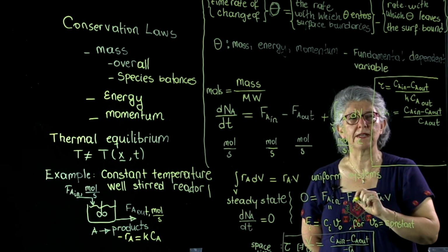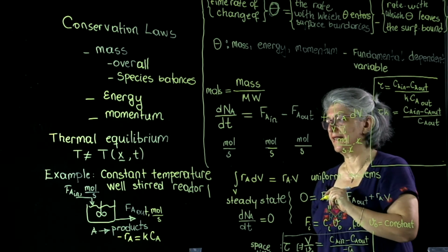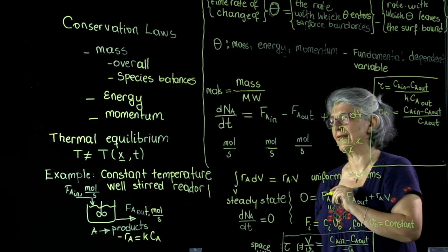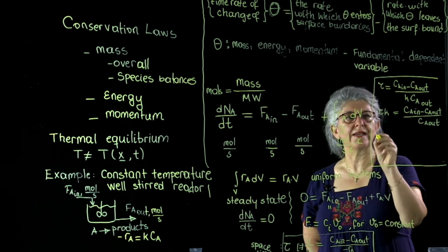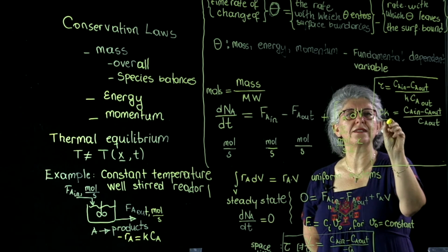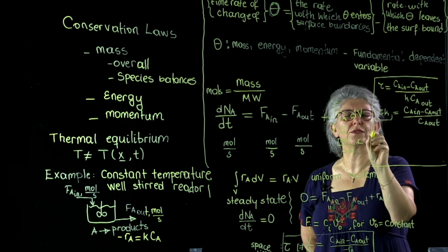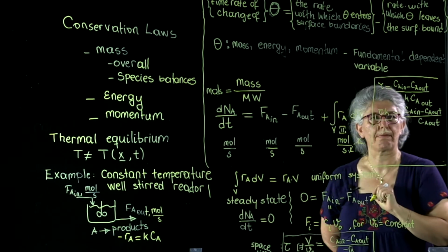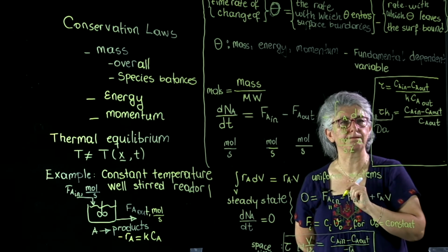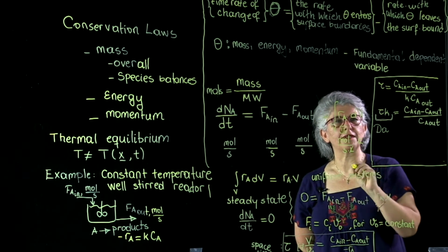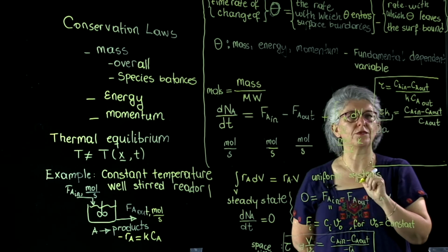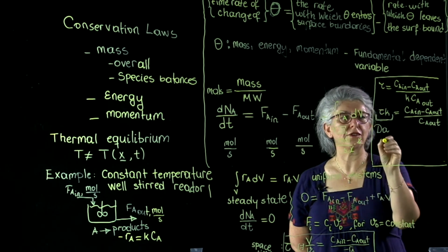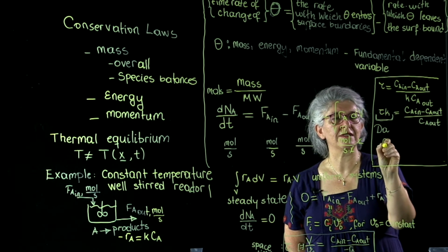Okay. The unit of K is 1 over seconds. The unit of tau is seconds. And tau K is a dimensionless number, which we call the Damköhler number. We will learn more about this. Now this equation, in terms of Damköhler number, can be solved for the outlet concentration.